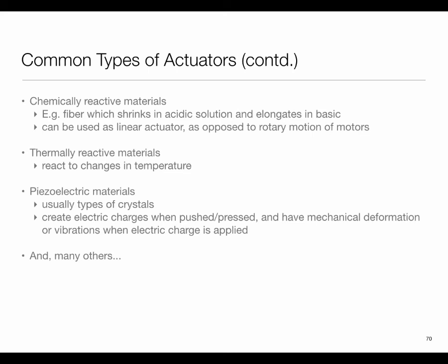One thing you would see is that many processors have two types of signals which target actuators. One type is D2A converters. They basically let you take a digital value and generate a voltage, so you can create a waveform which you can then feed into some electrical circuit. The other one is called pulse width modulation, which your embed has. They let you generate waveforms with the right duty cycles, and they are often used for motors and many other actuators. You'll find that platforms like Embed or Raspberry Pi usually have support for these kinds of actuator control signals also.